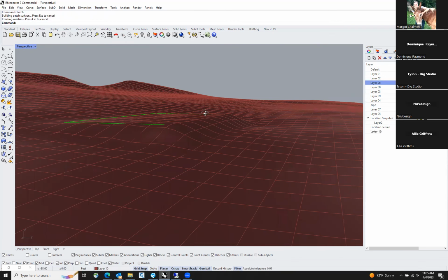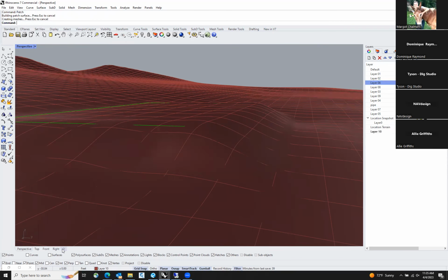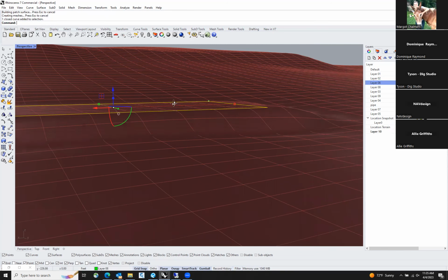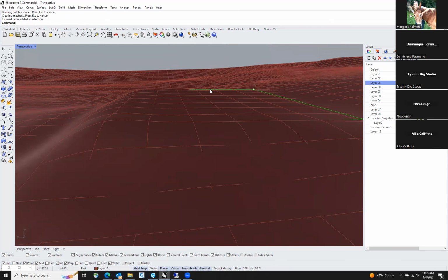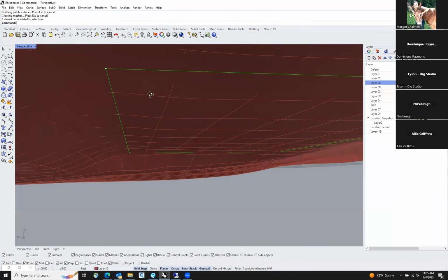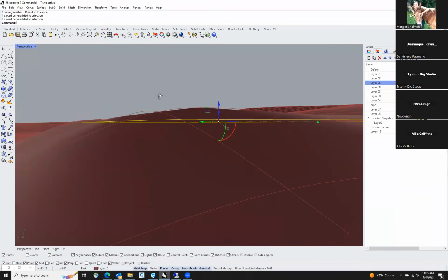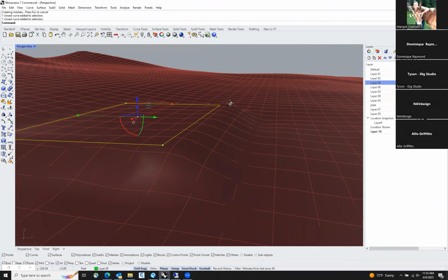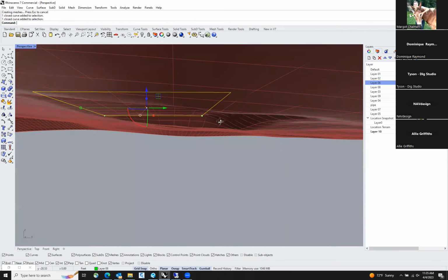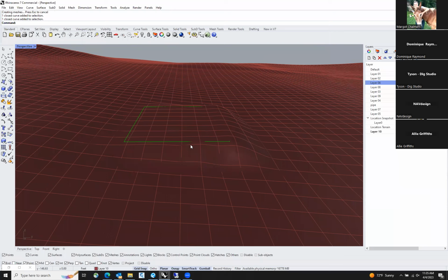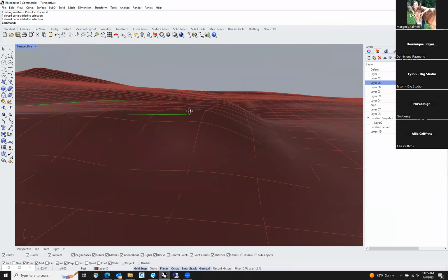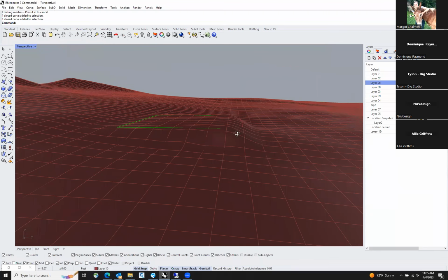You can now see that that building pad has been patched into this surface. But notice that that line isn't completely visible, it's actually underneath the surface, because that NURB surface was being interpolated from those points. So as you can see, you do lose some accuracy with the NURBs, but it does kind of take it and interpolate those side slopes for you.